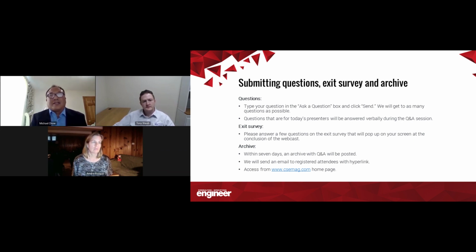Sure, that's a great question. One of the most complex lighting projects that we worked on was for a library, and they actually wanted to see the emergency lighting, not just the fixtures. There's what's called a point-by-point, which I think most electrical engineers are familiar with. It basically shows you the lighting levels, and there's a way with the software, you can tell it to provide the levels at a particular height, whether it's the workstation height or at the floor with emergency lighting.